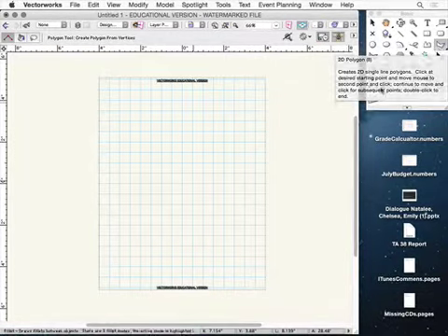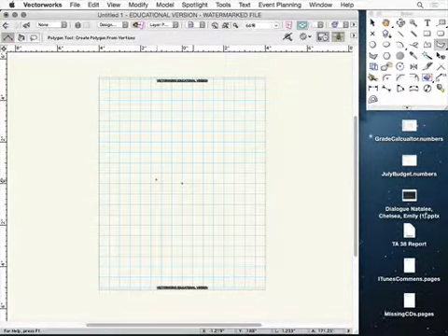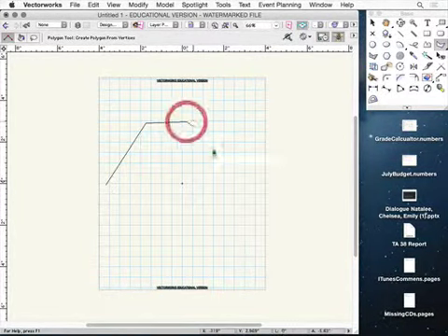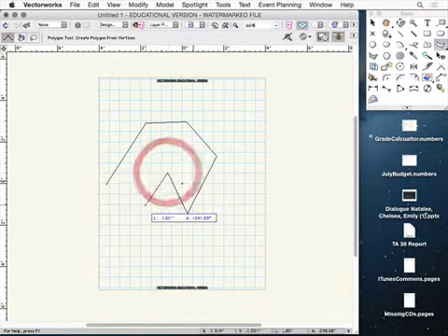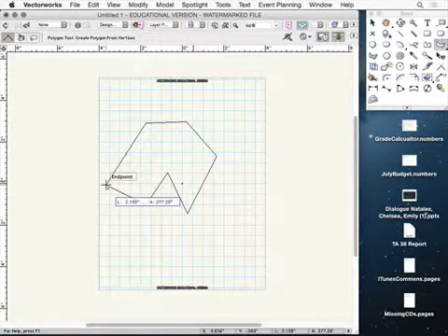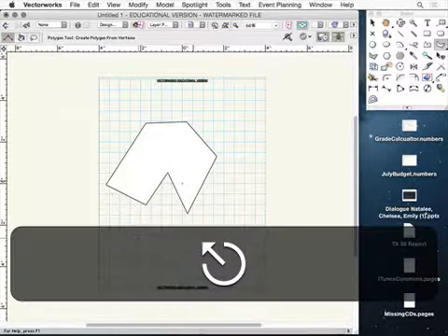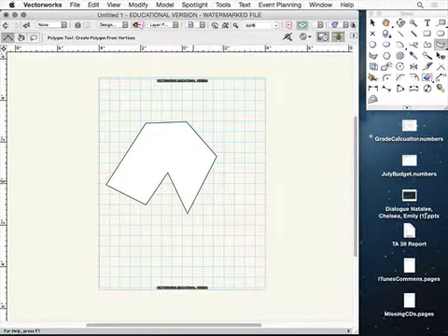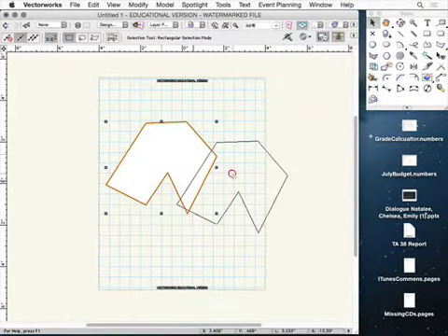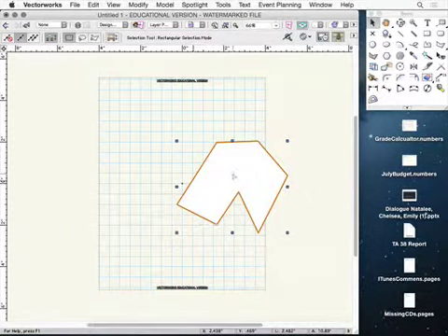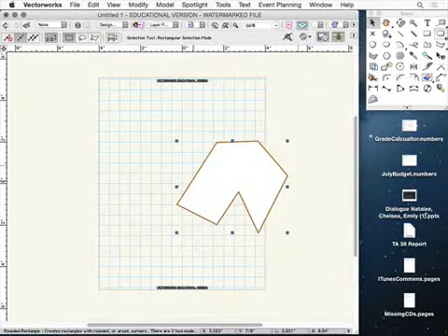So here's how the polygon tool works. It lets you draw a polygon. A polygon is a closed shape. So you draw lines, and you draw lines, and you draw lines. And then you need to get back really close to where you started and click. Whoops. Okay. Single click. And it will close the polygon. And this is now a closed polygon. Okay, very, very important. This will go into 3 dimensions nicely. Polylines do not go into 3 dimensions nicely.